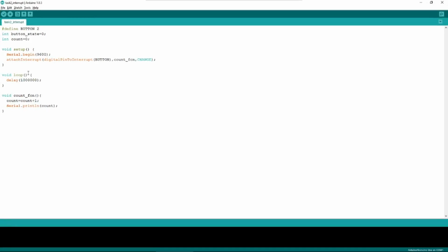So you may know that interrupt is some sort of signal, and there are different types of interrupt, for example software interrupt or hardware interrupt. As the name suggests, interrupts, that means it will interrupt some existing works. Let's say you are operating a motor using your Arduino, but there is a high priority signal to turn off the motor, let's say for an emergency. So to perform this high priority task, you need to use that interrupt. That means whenever that interrupt is issued, obviously all other tasks will be closed.